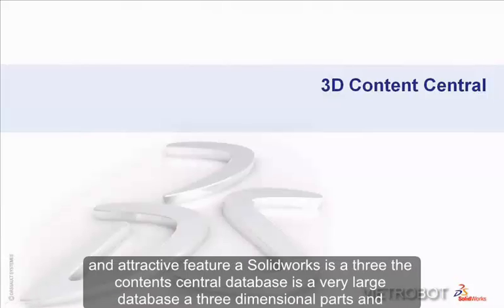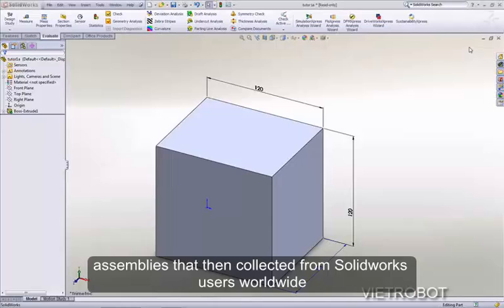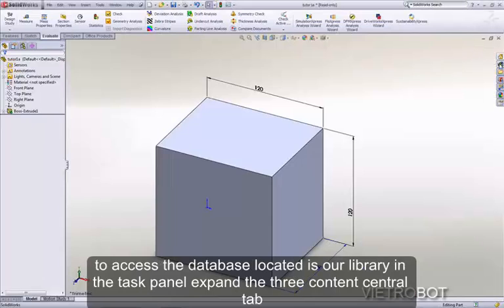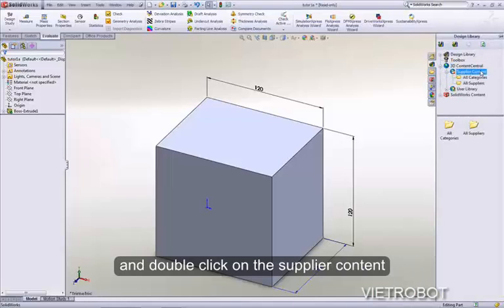An attractive feature of SolidWorks is the 3D Content Central database. This is a very large database of three-dimensional parts and assemblies that have been collected from SolidWorks users worldwide. To access the database, locate the design library in the Task panel. Expand the 3D Content Central tab and double-click on the supplier content.